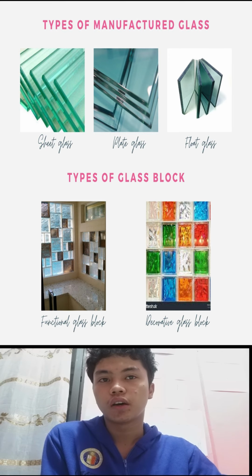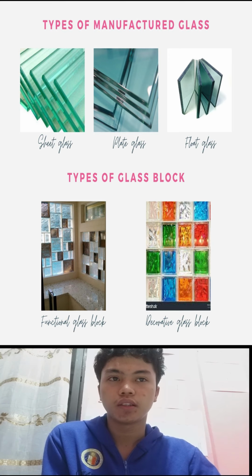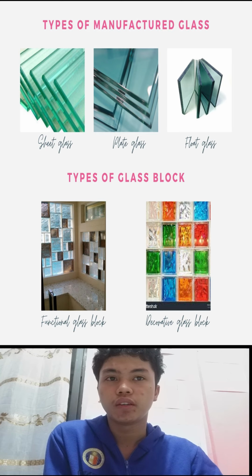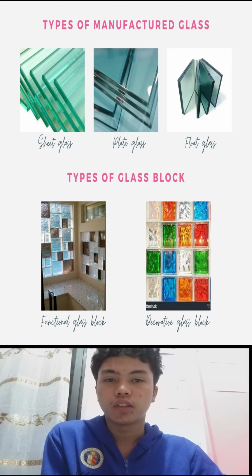Float glass. A float glass is produced by a new process. It combines the fire finish of sheet with the perfect flatness of plate. The usual combination of raw materials is melted in an oil or gas-fired furnace. The melted glass leaves the furnace and passes to a float bath where it is supported on molten tin. Gravity keeps the liquid tin very flat, and heat applied from above melts out any irregularities in the glass, which is free to conform to the perfectly flat tin.